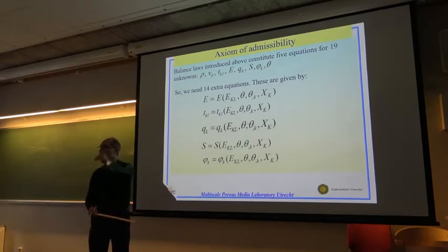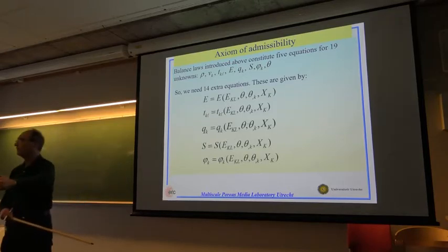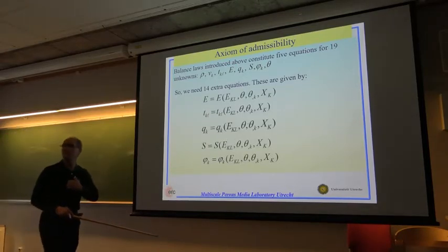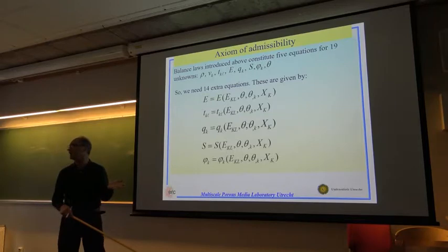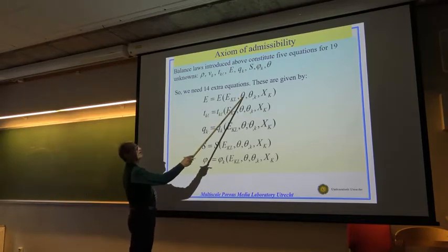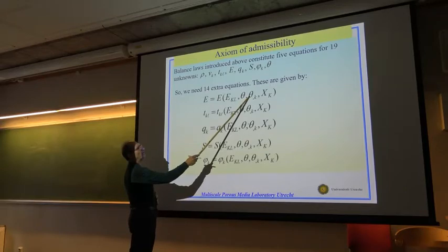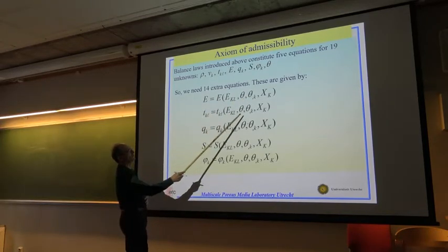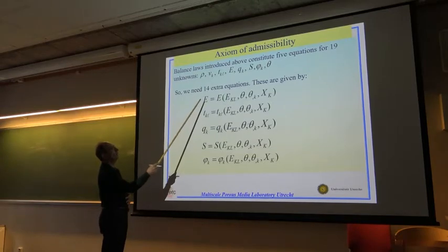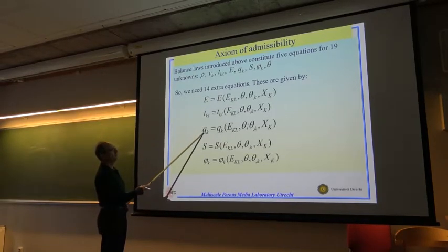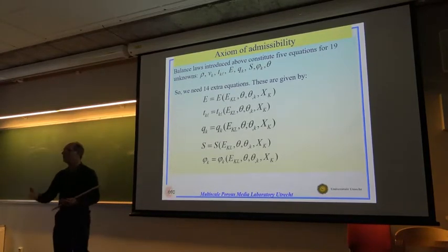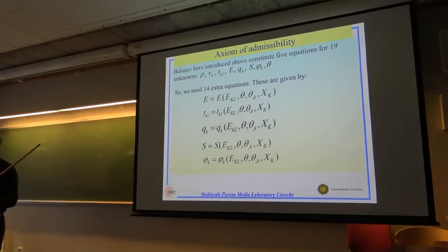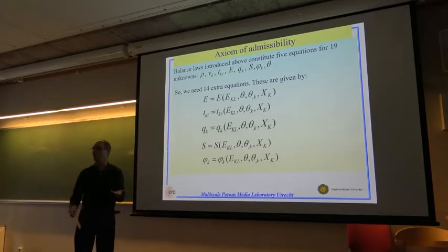There are very, very few materials with a thermal memory. I know perhaps some liquid crystals, I don't know what they are, but they have not been observed. So I haven't included that or the time derivative of temperature gradient. Stress tensor the same, and so forth. If you count 1 equation, 6 is 7, 3 here is 10, this is 11, 3 here, 14. I have enough equations, enough unknowns. You give me initial conditions and boundary conditions, I should be able to solve the problem. But of course, the form is not specified, so we need that.